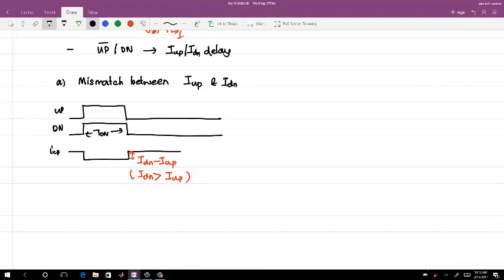If this is the profile of the charge pump, what do you think will be the case in the locked state? Think about it: if it is always giving you a negative current pumping into a capacitor, every reference clock, that means the capacitor voltage should go down in steady state. And if it goes down in steady state, you will not be in lock mode at all. So what should happen if you want to lock this? The negative feedback loop will take care of it. But how will this change the up and down signals?